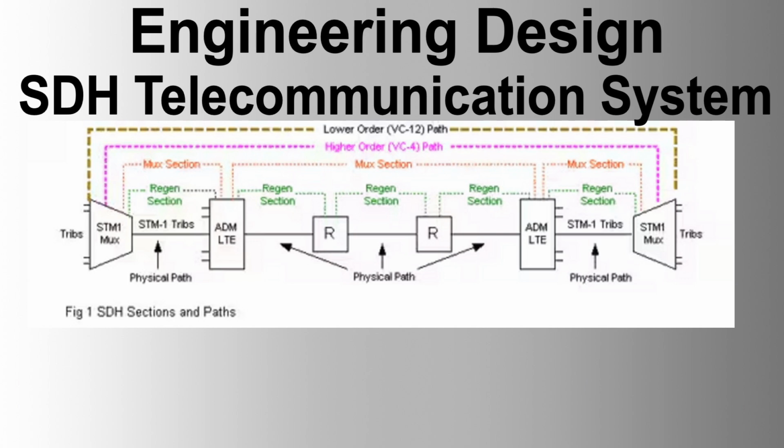Configuration control. The NMS shall allow for remote configuration of individual card options or connections, including switching from primary to secondary lines and loopbacks for troubleshooting. Server interface, interface development. The vendor shall supply a functional design specification document detailing the development and refinement of the NMS interfaces, including standards for screen layout, colors, fonts, navigation tools, and alarm reporting structure.